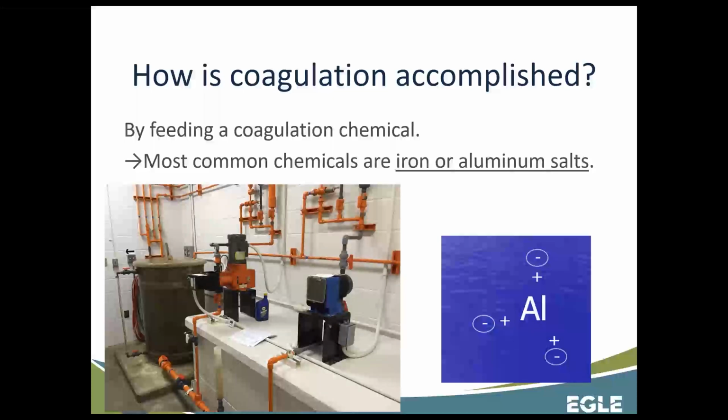It's important to have a calibration column. If you're relying on a scale or a flow meter, these are mechanical devices. They fail, calibrations go off. So it's nice to have a concrete way to know, yes, I'm feeding the amount of chemical that I think I am.